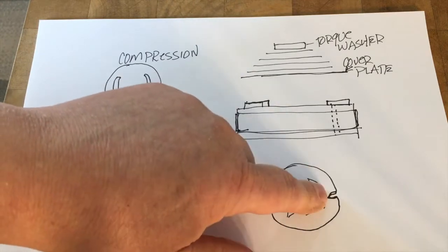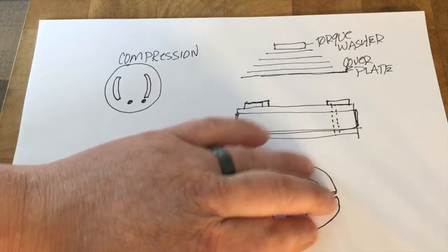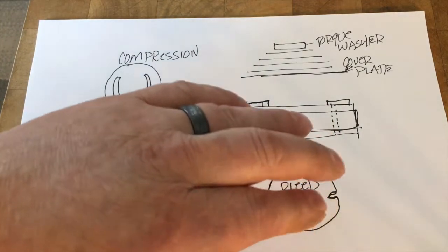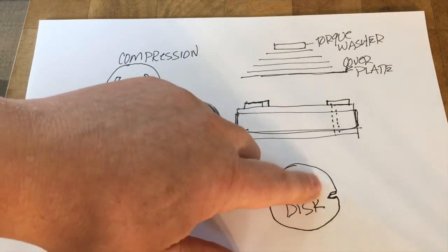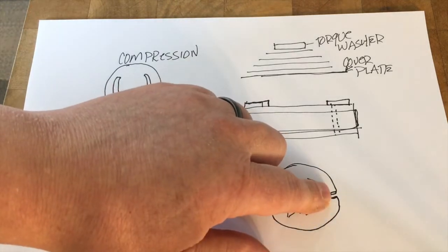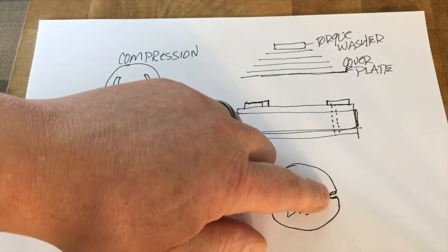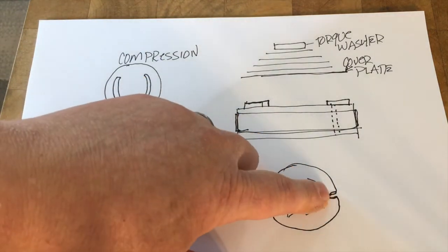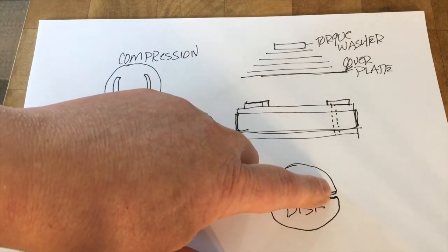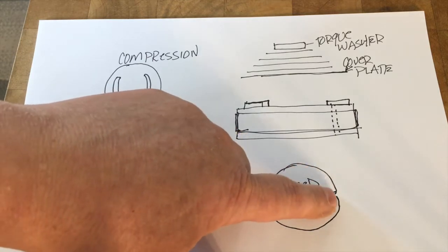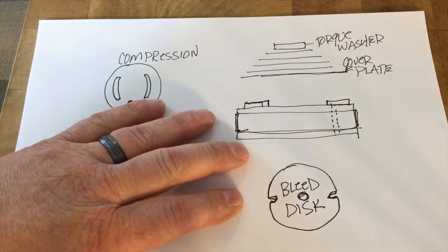The problem with stacking more of these up is you put a thicker series of plates in there, and your compression can get thicker or stiffer with the slots in there. So you could bleed off more, but then as soon as it starts coming off the bleed, you'll get a really stiff valve stack the more of these you put in there. And these will vary by thickness and stuff like that. I've even experimented making the bleed area here bigger with a thinner shim. I've done all sorts of stuff to play around with it.